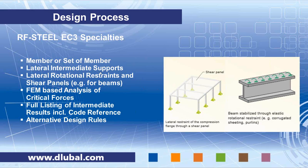A very important feature is the lateral rotational restraints and shear panels. For example, if you have a moment frame for a steel hull, and you can take into account the diaphragm that is stabilizing the I-beam against rotation, you can reach much higher critical bending moments, and therefore you get higher critical values and a better design ratio for your stability design.